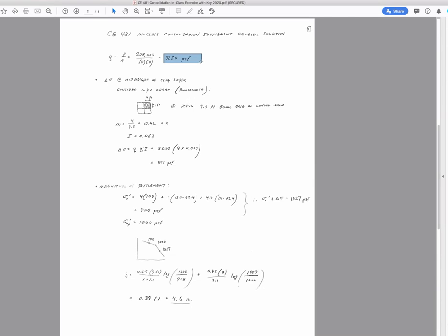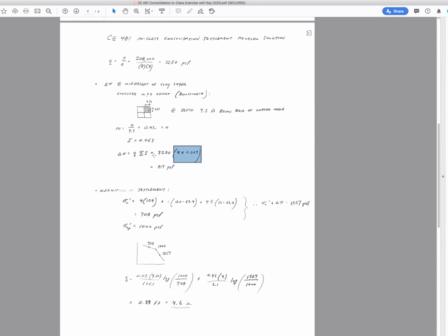You don't squish it down to a smaller, the load isn't being carried by a smaller size. We're just compartmentalizing that into 4 pieces. And the summation of influence factors here would be 4 times that individual component. So 0.063 gives us the effect of that shaded region, and we have 4 such shaded regions. And I came up with 819 PSF for a delta sigma at that location.